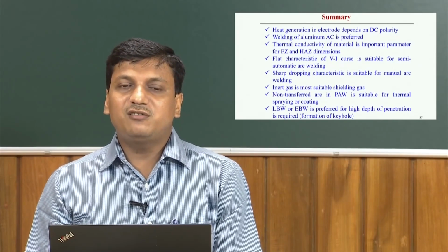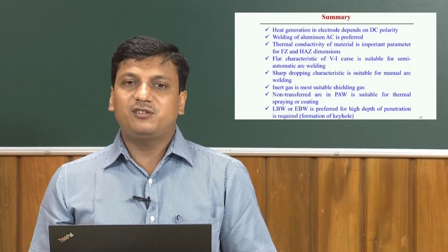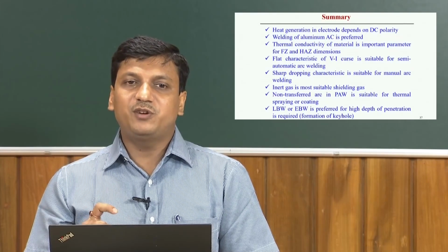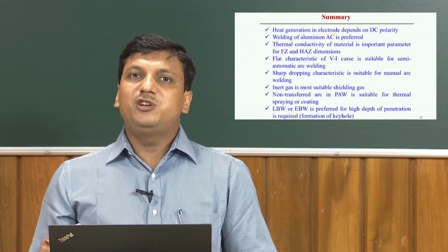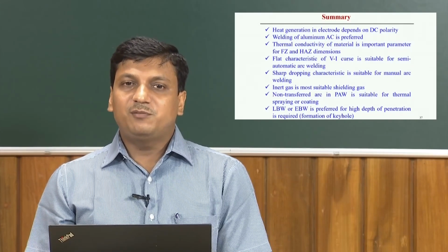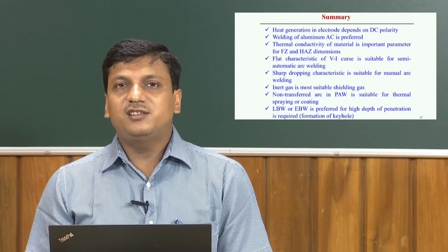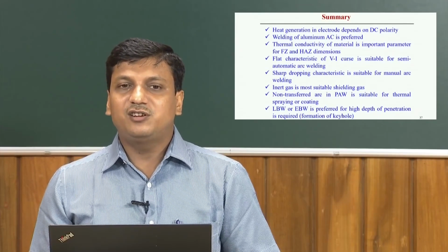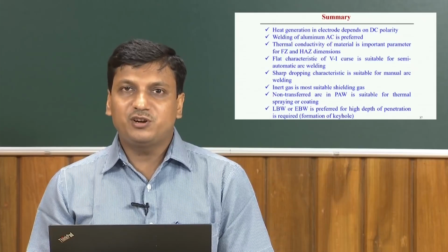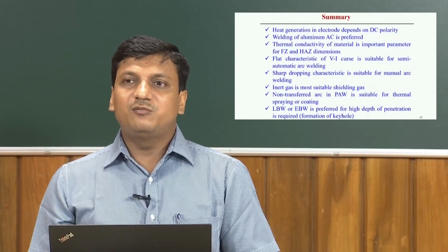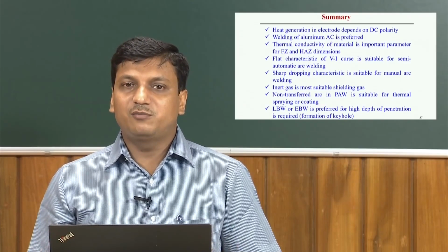And laser beam welding or electron beam welding is mostly preferred when there is a requirement of high depth of penetration and minimum heat affected zone and minimum fusion zone. Definitely, laser beam welding and electron beam welding produce high depth of penetration through the keyhole mode, the formation of keyhole mode welding processes.